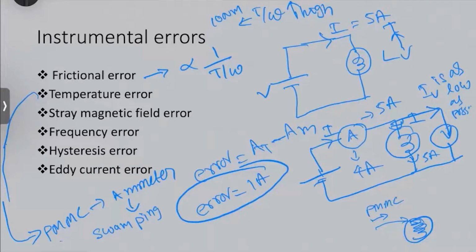Reduced by connecting a swamping resistance in series with the ammeter. Yes, swamping resistance in series with the meter.